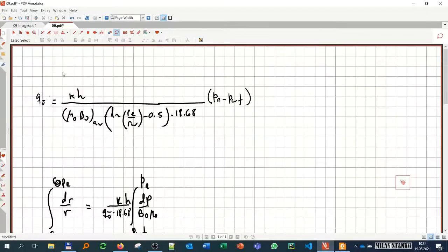Earlier we derived this equation, the analytical IPR equation, which was derived from Darcy's law. We assumed steady state, a vertical well completed through the whole interval, and a cylindrical region draining from the center, which is undersaturated and at steady state. That means that at the external boundary RE, you have some mechanism that is keeping that pressure constant, so you need to have some mass influx into the volume.